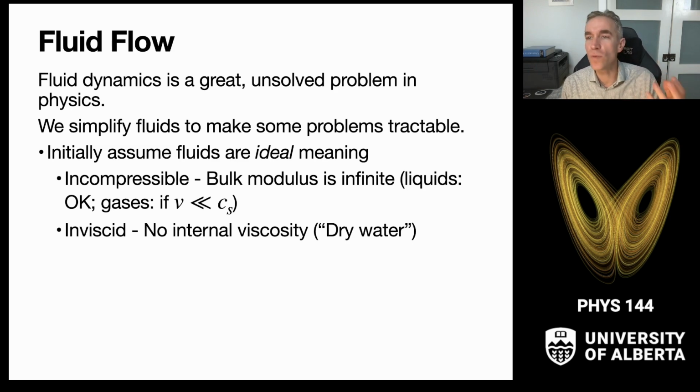So it's a reasonable assumption, and this just means that the pressure forces inside there can transmit changes quickly, and so the pressure will balance out the forces inside the fluid faster than you can change the shape of the fluid. So if the fluid flow is less than the sound speed, then you'll probably get pretty close to incompressible physics. The other thing is no internal viscosities of the fluids.